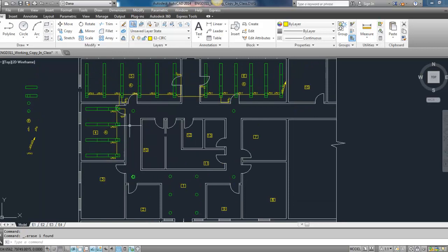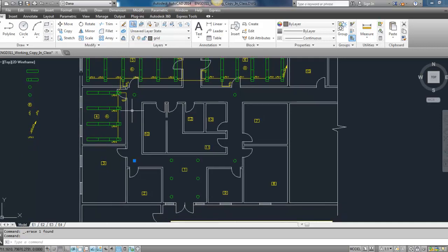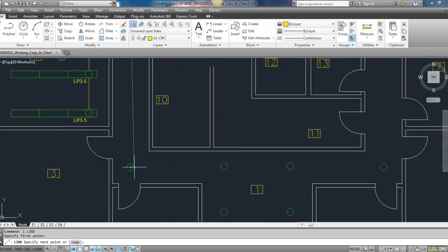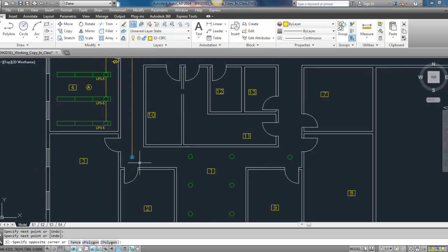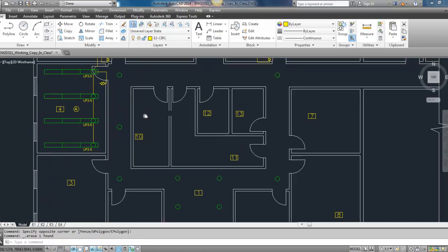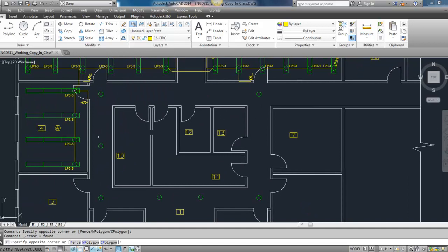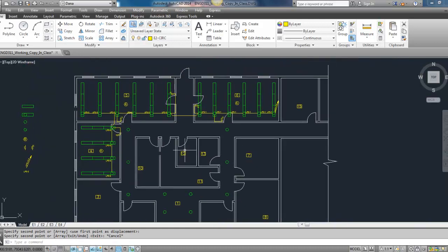However, I don't think these lights are powerful enough to throw light all the way down this hallway. So I'm probably going to place another one roughly halfway in between. Now, it's not going to be rough. I'll be able to get an exact calculation if I draw a line. I'm going to place another luminaire at about the halfway mark between those 2 luminaires. Same thing on this side, so I can just copy this one now that I've done that. And that will lay out this part of the hallway.